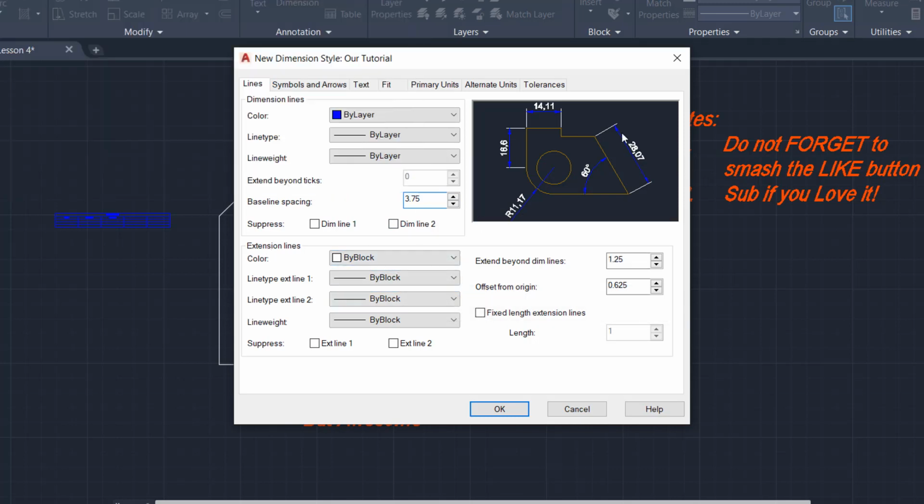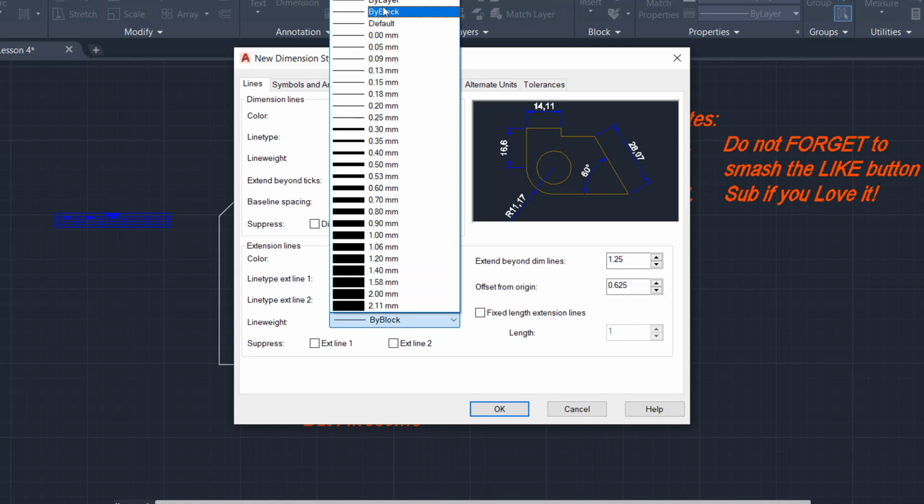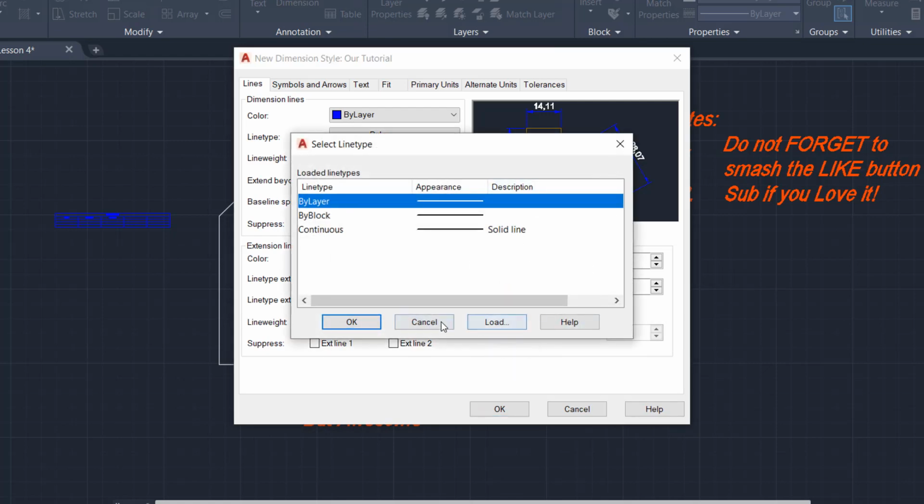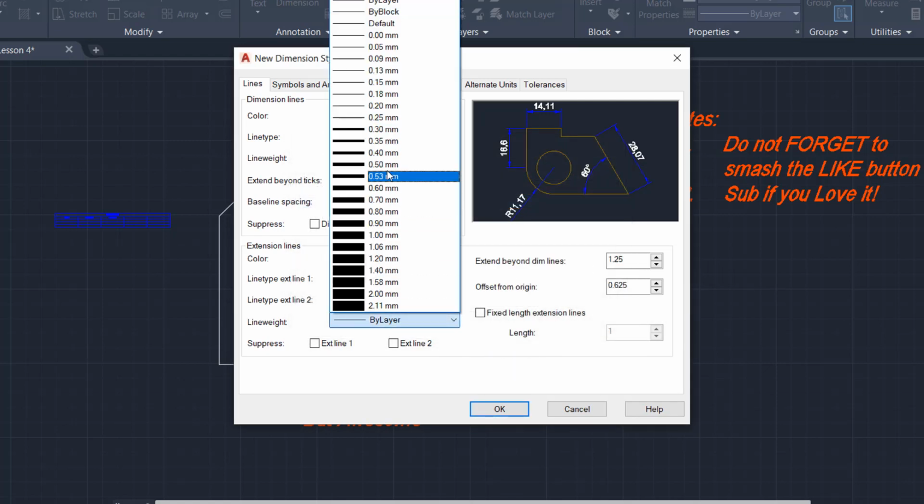Extension lines are these vertical lines here, again all set by layer. But you can work through all these settings. For example, line type EXT line 1 is for one side of these lines. 2 is for the other side. In line type, you can make a dashed line, dashed and dotted, and etc. Line weight is for making it thicker.